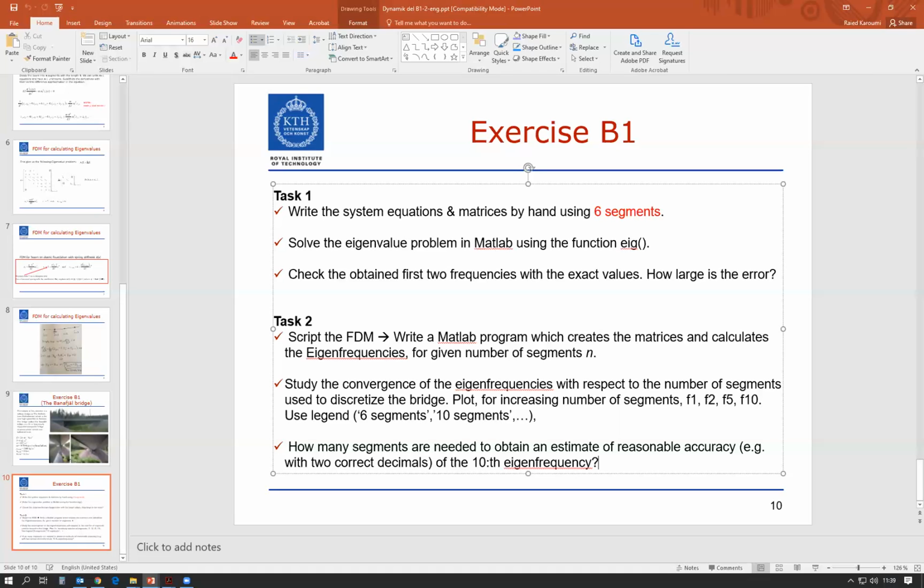How can you consider the contribution from the soil? Because the soil itself will contribute to damping, and it will also contribute to added mass. So part of the soil will actually also be bouncing with the bridge in the different mode shapes, which contributes to added mass. And we know that if we increase the mass, we will decrease the amplitude of vibration. That is also something we talk about on Wednesday.